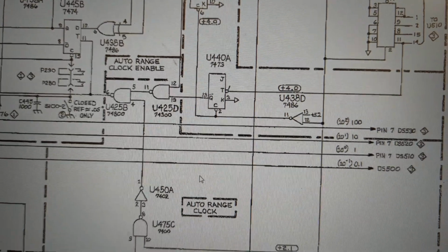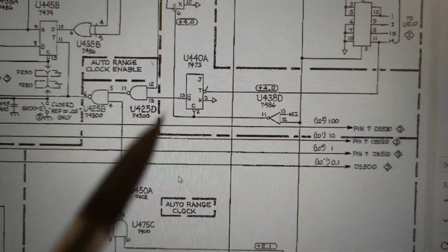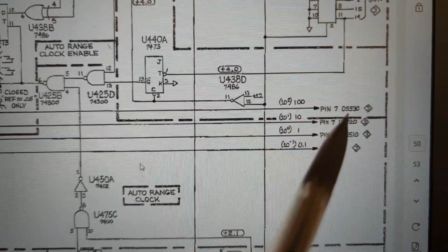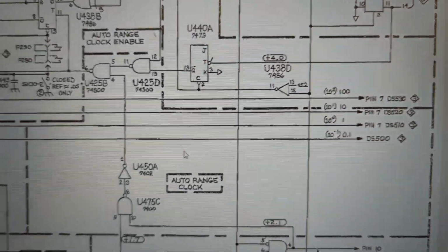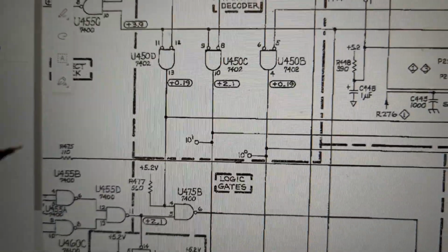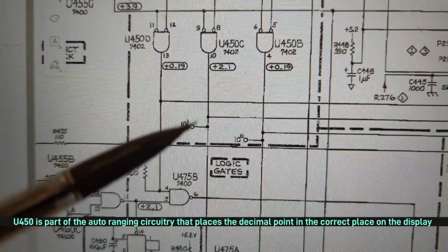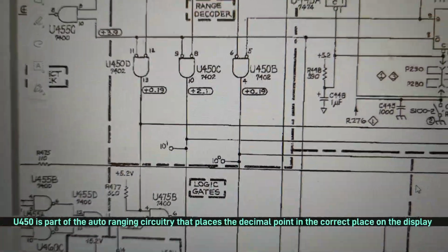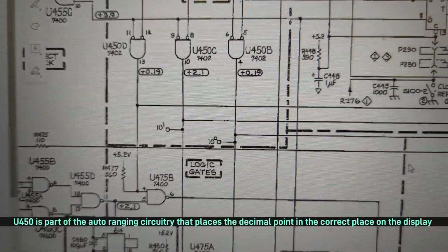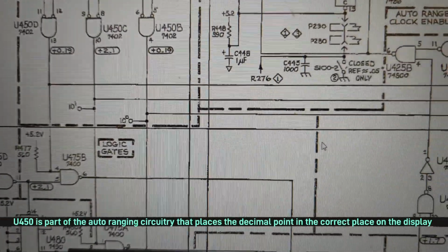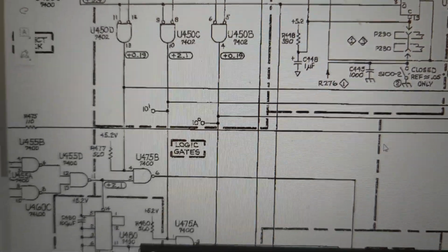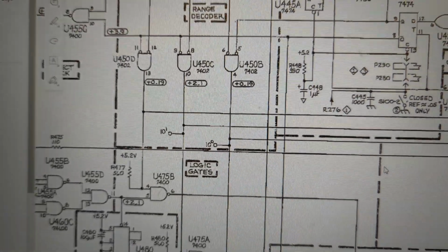That goes directly to another interesting thing, pin 7. These are the 7-segment displays, so it's an important part of the schematic for driving these 7-segment LEDs. So I don't know. I'm going to pop it back in and chase a few other spots on the circuit that don't match up, but I just wanted to point that out.